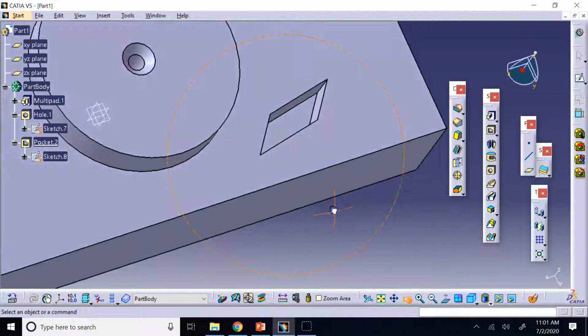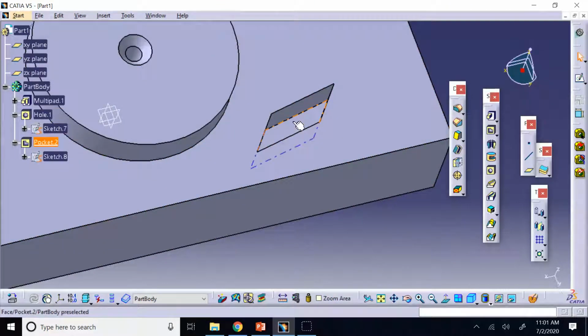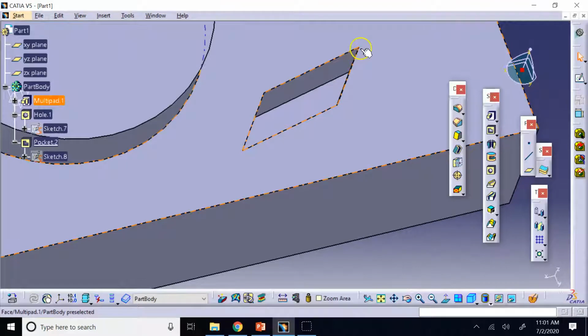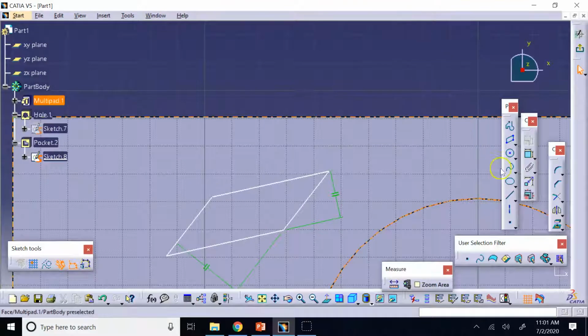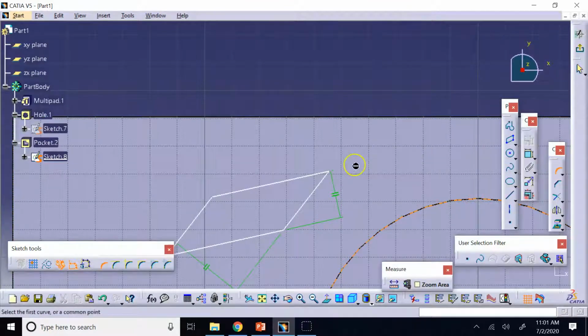But when you want to create that in a CNC machine, it's not just that easy. So remember, whatever that you create in a CAD software very easily using these tools, it doesn't mean you can replicate in the real world using the machines that we have. No milling machine can ever give you perfect sharp corner like that. You always need to separate a small amount of radius for the radius of the mill tool, okay? So if you really want something like that, then the closest you can get in real life is if you do fillets on the sharp ends, okay?